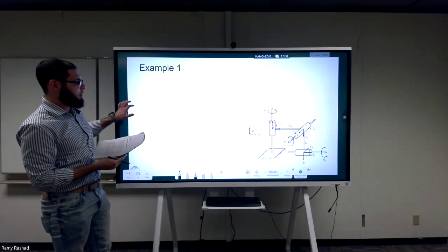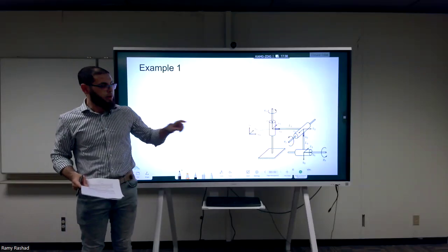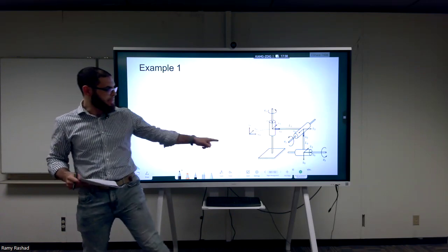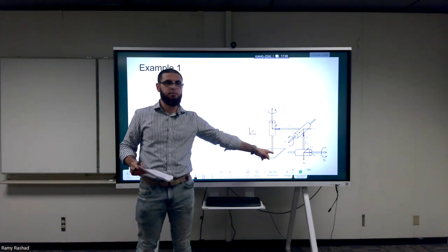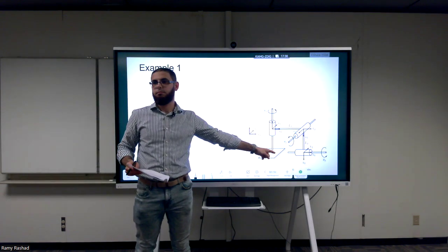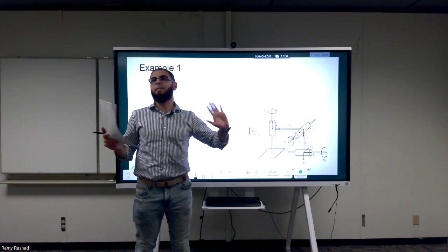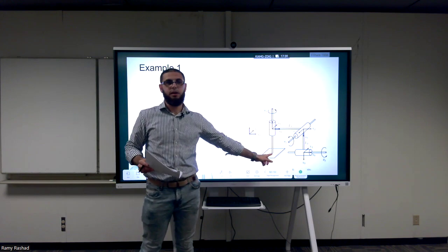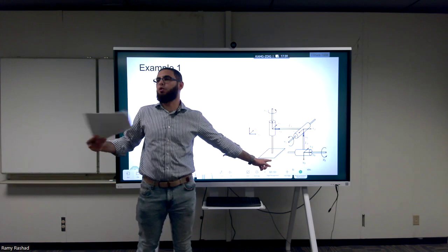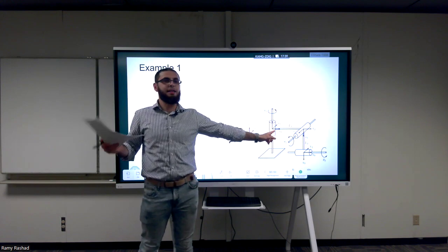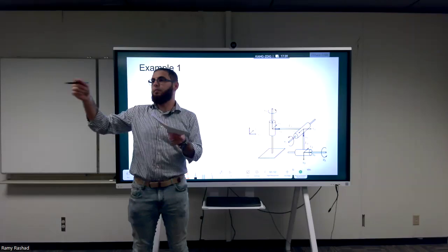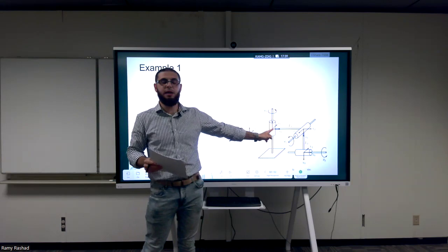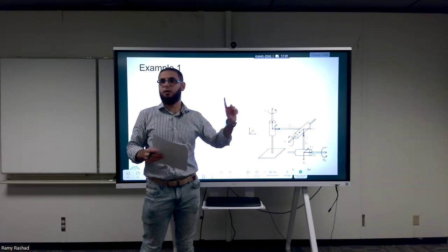Now let's see, where is the stationary frame? It's placed up here. Why not there? It's going to make our life easier. Think about this zero frame being there. We just add a new zero frame, let's call it zero dash, and we put it there. Having a constant transformation between any two frames is very easy, just a constant homogeneous transformation. But when we put the zero frame here, it will make our life very easy, and you'll see now why.